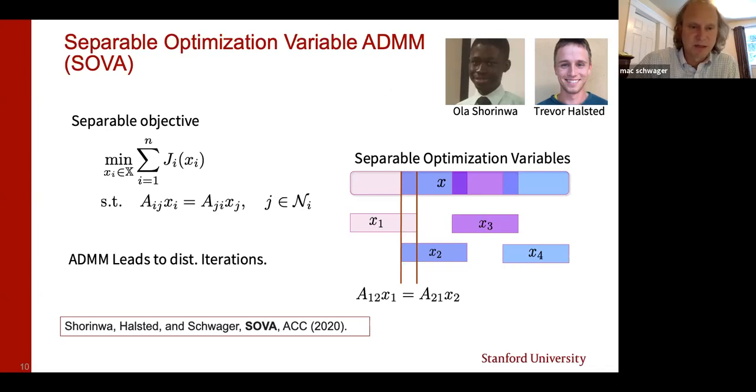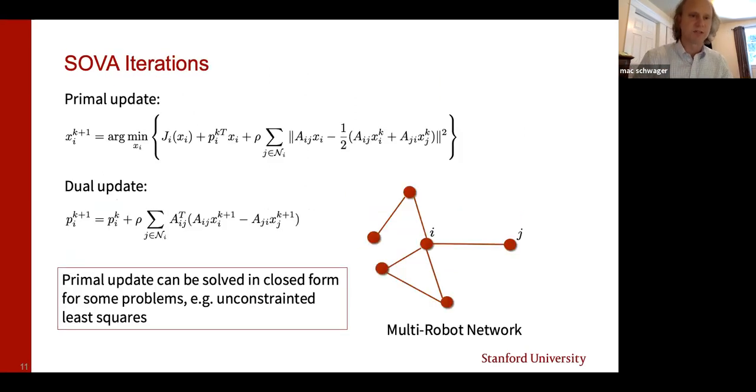And we turn this ADMM crank. We formulate the separable objective in a way analogous to consensus ADMM, and we end up with these two steps. So we have the primal update, which, now you can see it in more detail, is the smaller scale instance of the global objective. So this is performed entirely by robot I, and it only requires robot I's component of the objective.